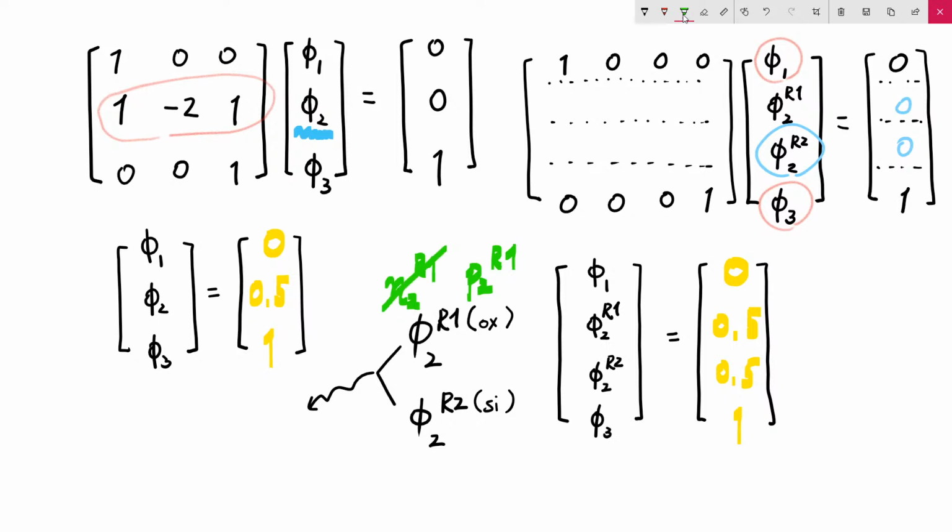There is nothing like this because the oxide region does not have electron density and hole density, since the oxide is regarded as a perfect insulator. However, if we consider this one, then we will have N2R2 and P2R2. They have really good physical meaning, and we really want to solve and get those numbers. So, are you with me?